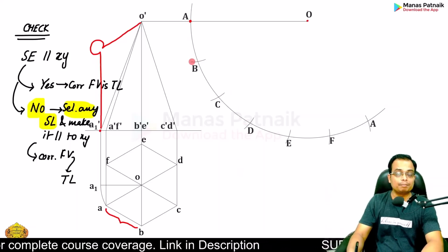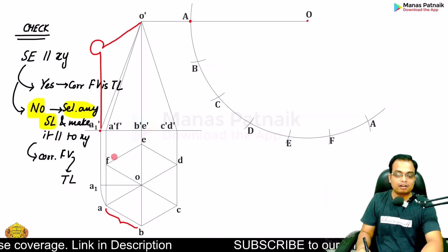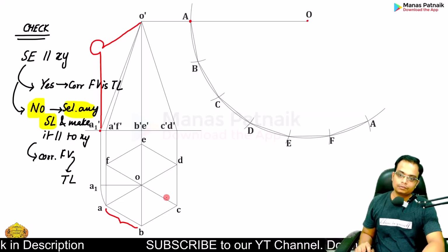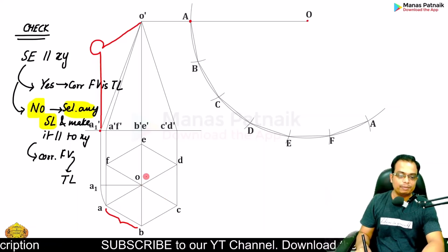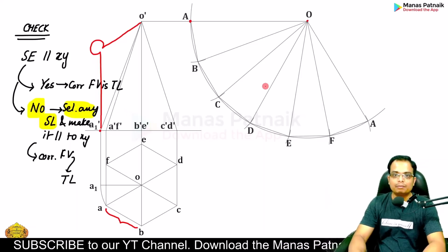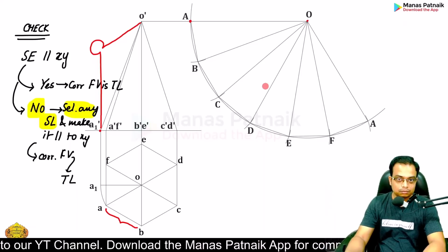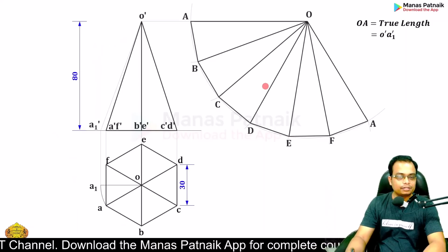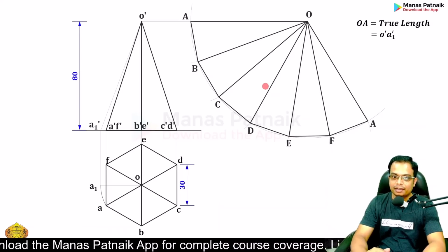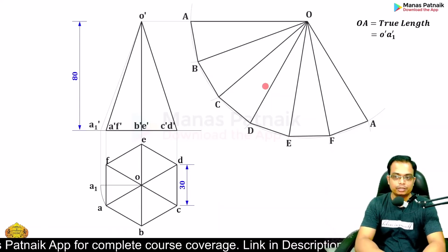This is the case of a pyramid. So all of these base points are connected via straight lines. Join them. Now make these slant edges, CO, DO, BO. Done. Development is done. If you want to make your work look more professional, keep the dimensioning dark, and keep the construction stuff very, very light and grayish. This is the level that you need to achieve.